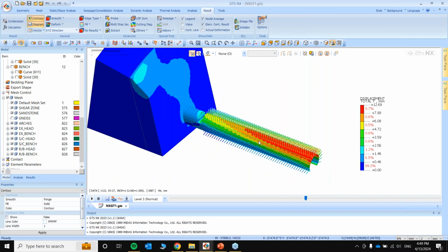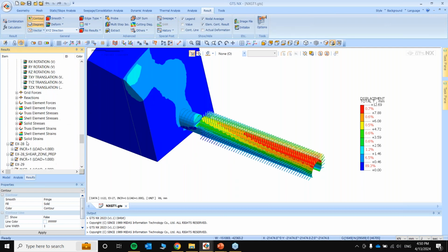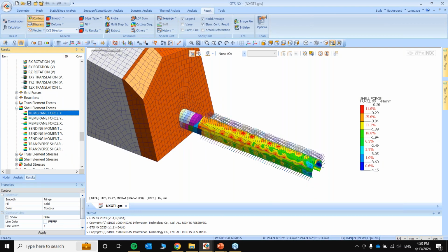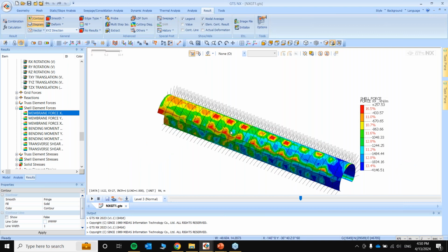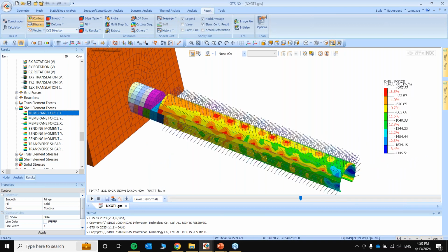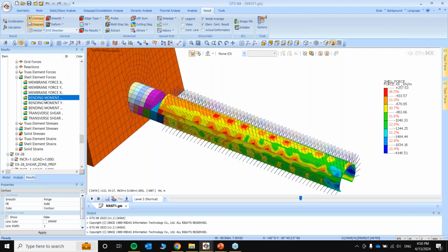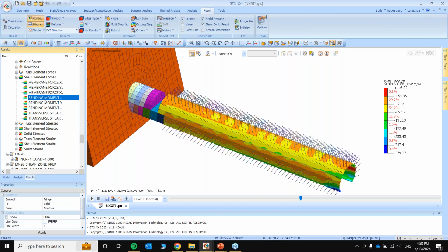Now, naturally, due to the change in the overburden, you can expect the stresses to be extremely high on this part and this part as compared to this part. Next, the forces on the hoop stress on the liners. Let's change it to kilonewton per meter. So right now it is more or less uniform, except near the boundaries. The bending moment, then the transverse shear force.